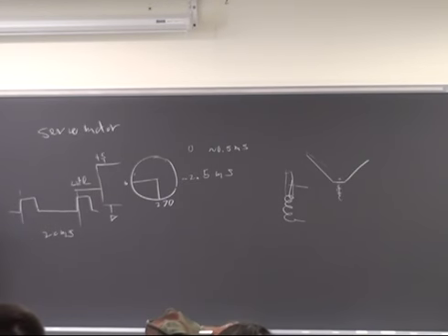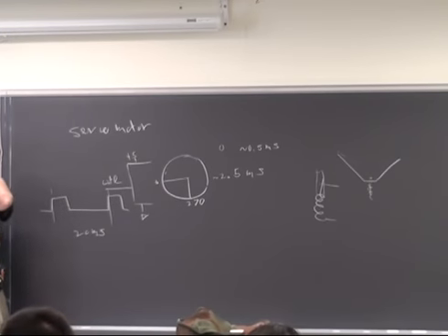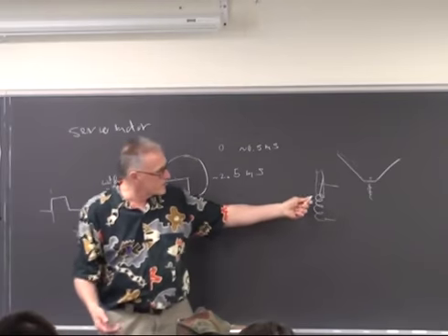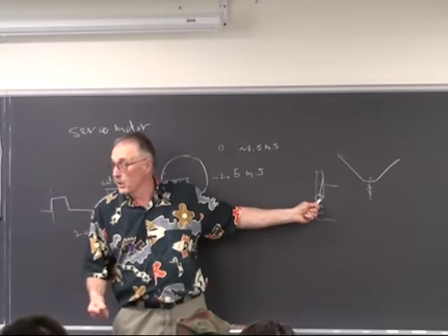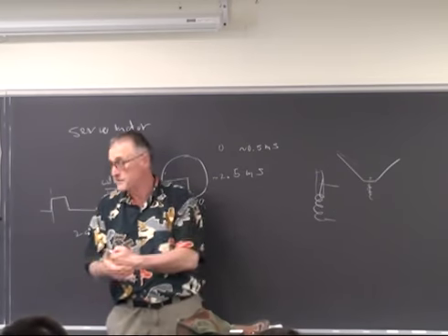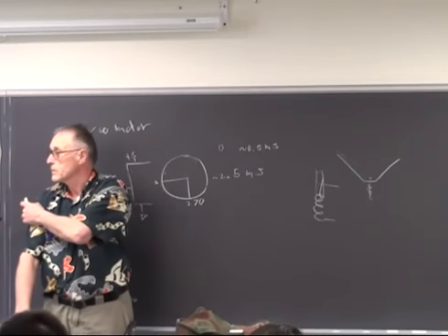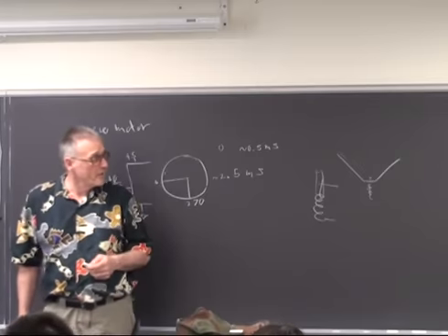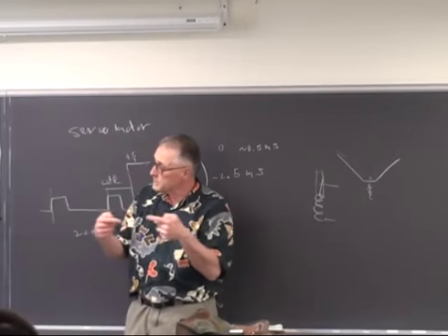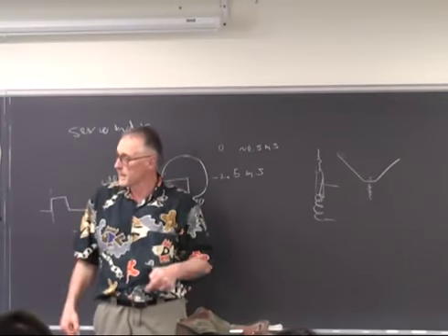To a small extent, you can control how fast it is by the current you put through the solenoid. But basically, you get up to some threshold, and the armature snaps into the coil. Partly because once it starts to move into the coil, the field gets greater, it moves faster, so you get a feedback situation that drives it into the coil. If you have two coils, you can control them in two directions, but usually there's some sort of spring out here that pulls it out.